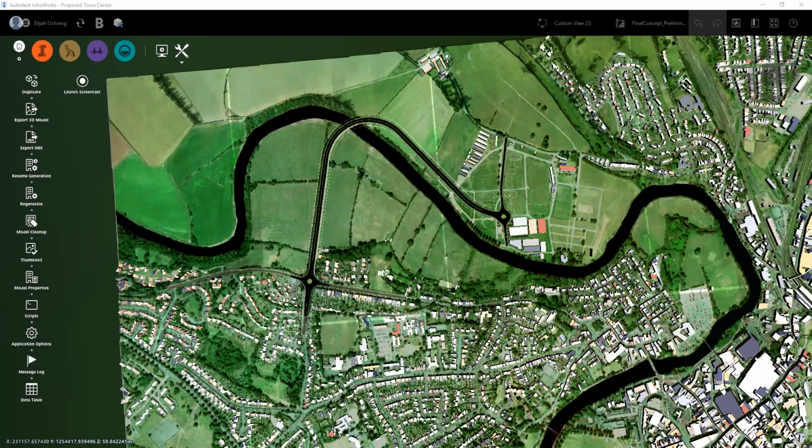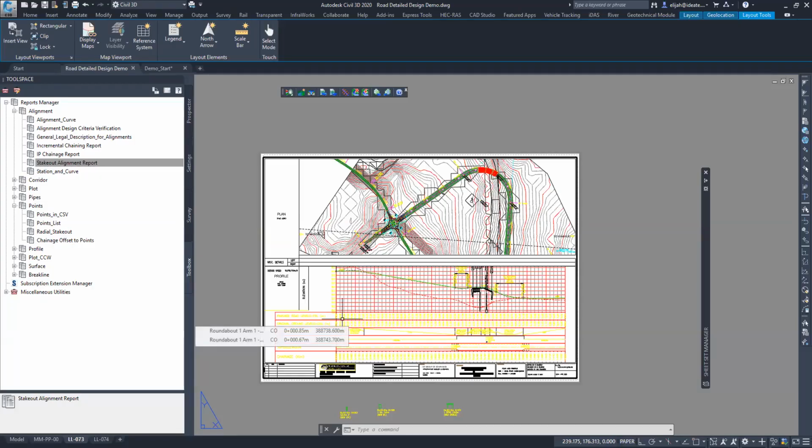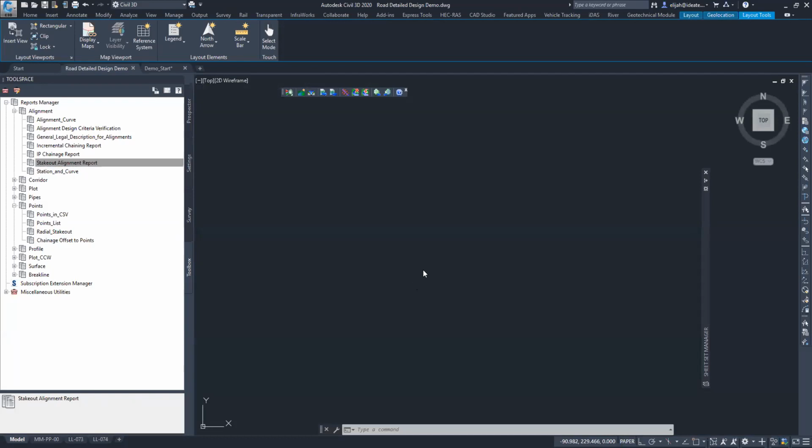But as an illustration, within the same project I was showing you, there was a volume report that I had generated side by side with the design. So if I can just switch the screen shortly, you'll be able to see that with Civil 3D you can generate both the earthwork volumes, that is cut and fill, and you can also produce the pavement structure volumes, that is the base, the sub base, and the finishes of the road, whether you're using asphalt or bitumen. You can produce those in a table and print them into a format that can be used for the construction process.